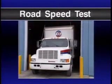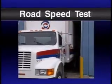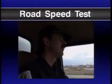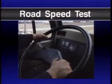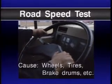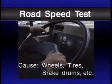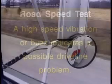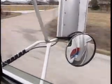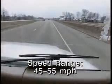If there is no vibration, then you should do a road speed test. To do a road speed test, drive the vehicle through the speed range where the vibration occurs. If you notice a low-frequency vibration, such as a shimmying or shaking, the cause is probably a wheel, tire or brake drum, axle shaft, or wheel bearing. A high-speed vibration, or buzz, indicates a possible driveline problem. Usually, a driveline vibration shows up at a specific speed range, for example, between 45 and 55 miles an hour.